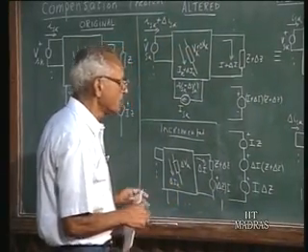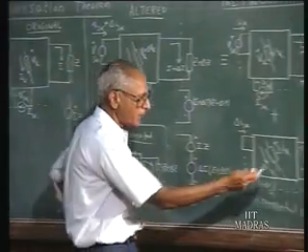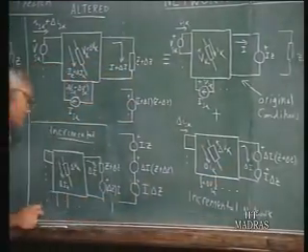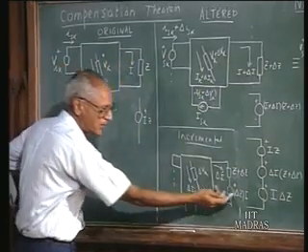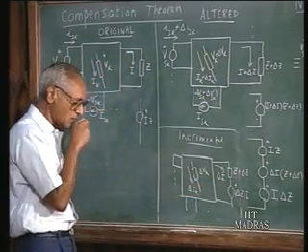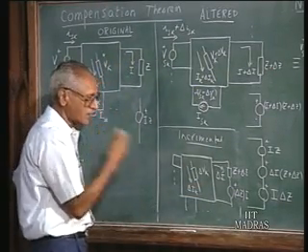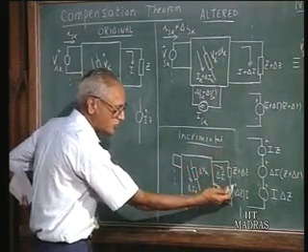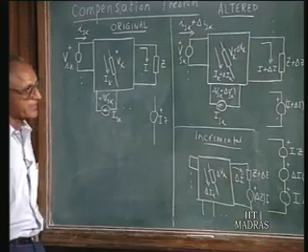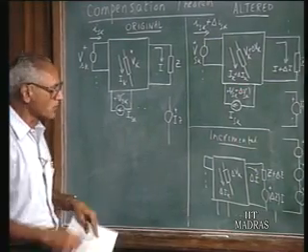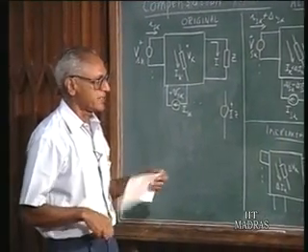Apart from this, you must also keep in mind the polarity of this incremental network. This is the incremental network. Original current was in this direction. So for delta Z times I, if delta Z is positive, the source should be such as to drive a current in the opposite direction. This is something which we already mentioned. So let us work out an example to illustrate this idea.